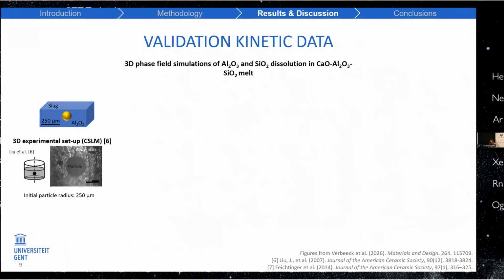So what we did was we used this input to perform three-dimensional phase field simulations of alumina, but also of silica dissolution in this ternary melt. And we did these three-dimensional simulations, and we compared them to experiments, CSLM experiments, confocal scanning laser microscopy experiments on the dissolution to get a better view on our results.